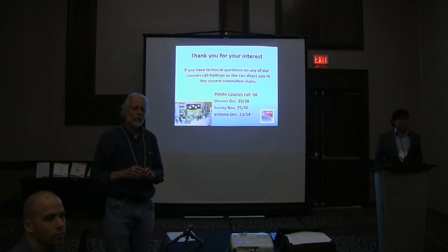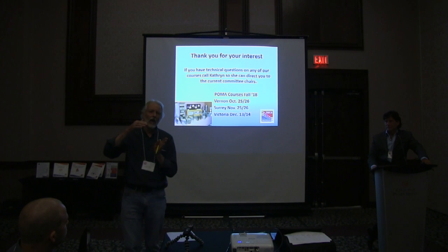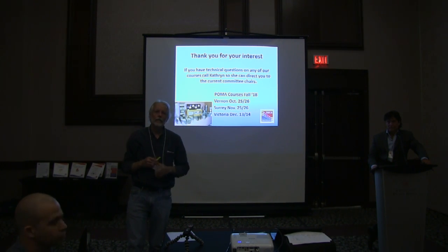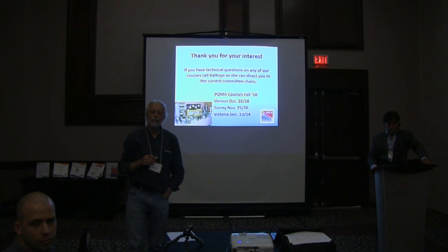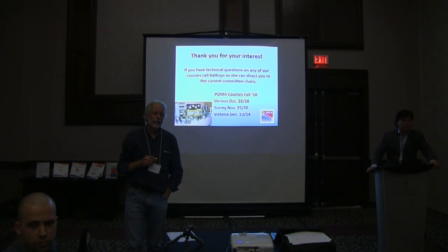Most manufacturers will have a table with the CFM inputs and pressure drop. So you just put in a pressure drop and look at the pressure drops. You'll be horrified if you look at those tables and you're running at 0.8 of an inch. Your wattage on those ECMs would be right through the roof. That's what I suspect. I wonder if some of the complaints people have about their high electrical bills going up when they put in a new gas furnace, they're kind of wondering what's going on. The house is shaking, you kind of know.